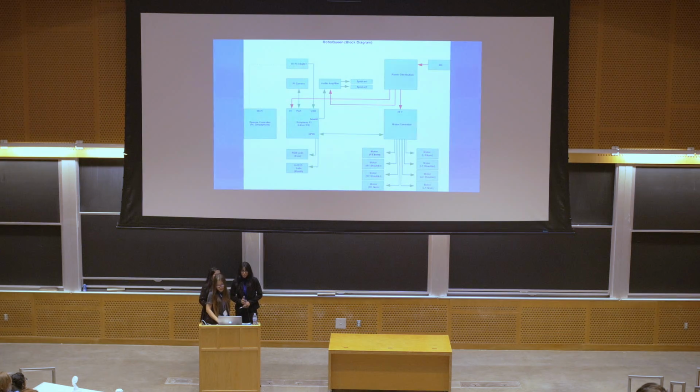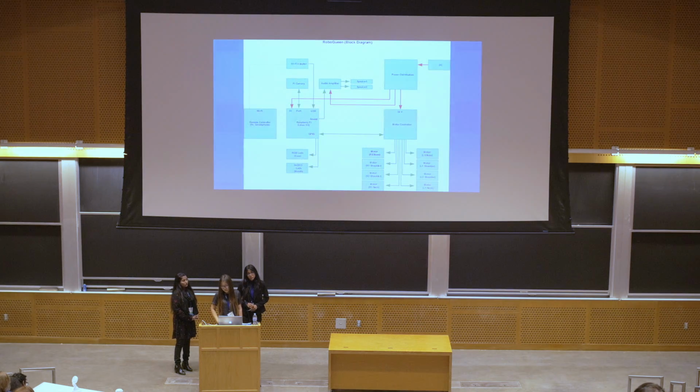A life-size interactive robotic mannequin prototype was designed and developed with low-cost open-source hardware and software, with an emphasis on using readily available off-the-shelf construction material and hardware devices. In our block diagram, the main component is the Raspberry Pi, which connects to a motor controller that controls 8 motors, 2 in the neck and 3 in each arm.